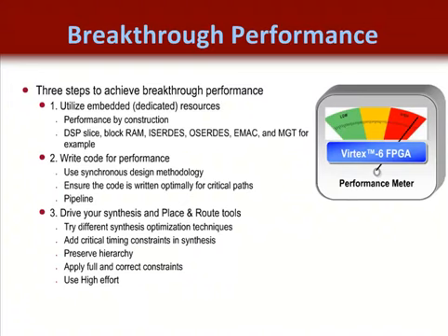Many new customers are disappointed that they're going to have to instantiate some of the most popular FPGA resources into their design and that their synthesis tool won't infer everything they want. Well, this is now pretty much standard operating procedure in the FPGA industry, and what I mean by that is that most customers are prepared to create highly optimized cores with the Xilinx core generator or the architecture wizard utilities, and then instantiate those components into their HDL.